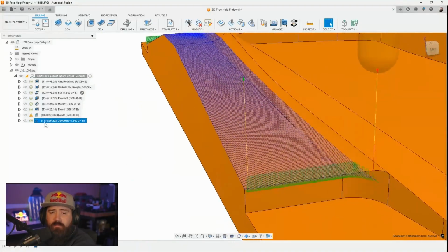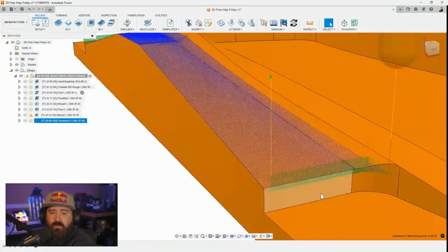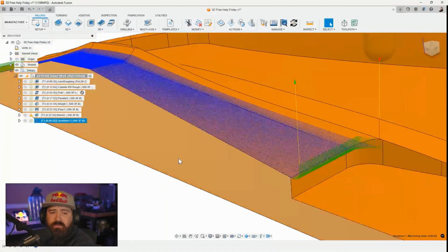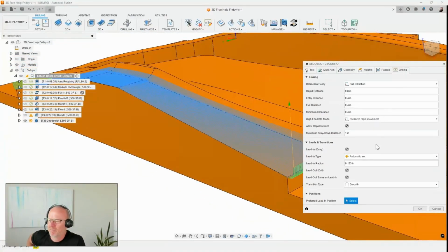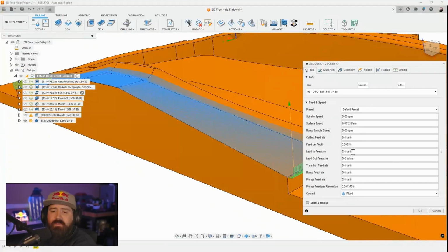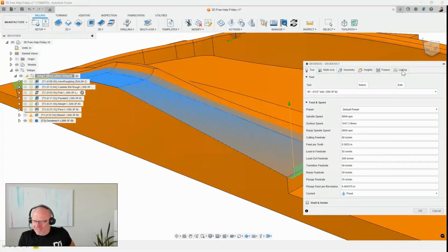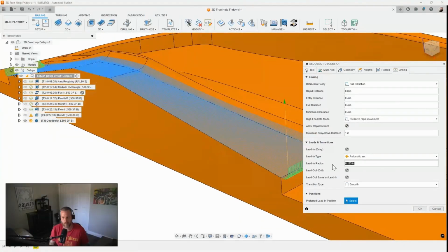I think geodesic is probably slower because of all these big lead-ins and lead-outs on the ends. Yeah, part of it. Mostly. And the feed rate would be different, perhaps. Like the vertical feed, probably the same. I think it's the same. Okay. Yeah. It looks like there are more segments as well on that upper fillet.